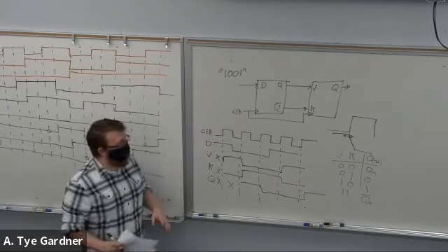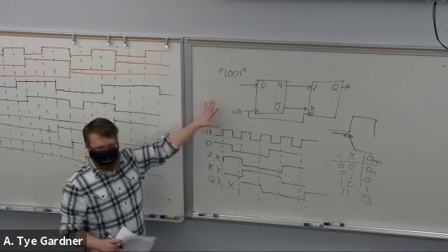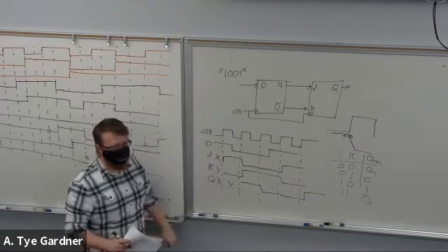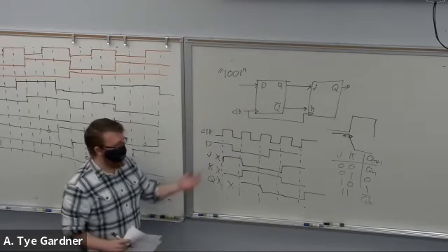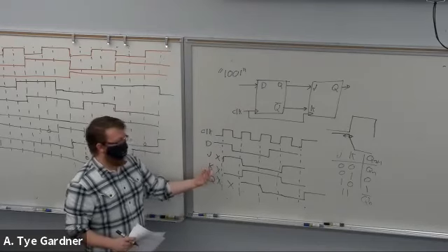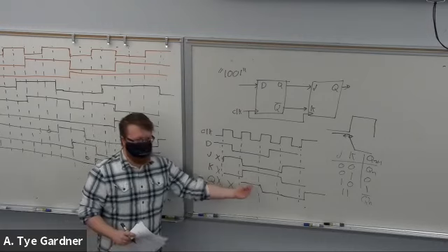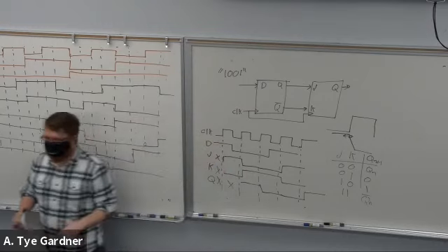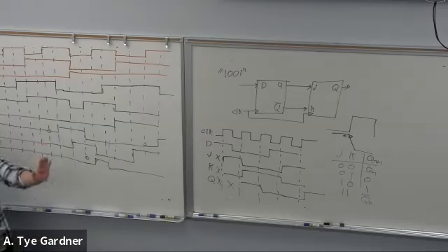Right. Expect some sort of question like this with at least 2 connected flip-flops, right? That you're going to have to do the timing diagram with clock delays. May or may not have clock to Q as well, but you'll at least need to offset it by 1 clock phase. Yeah. I have a question.